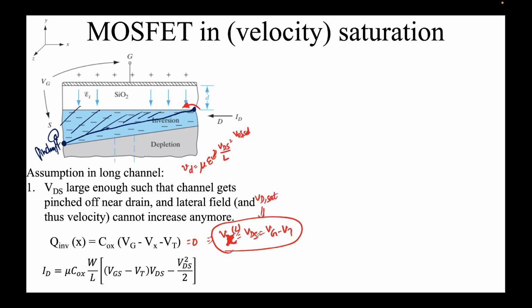And you put this VDS over here, and thus you get that good old expression, (VGS minus VTH) whole square by 2. Put VDS equal to Vg minus Vt over here, you get this. This is a constant value, it's not depending on VDS, hence the current saturates. This is the story in a long channel.